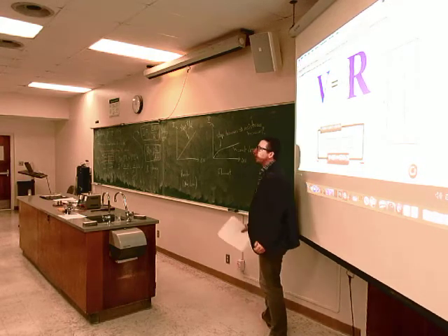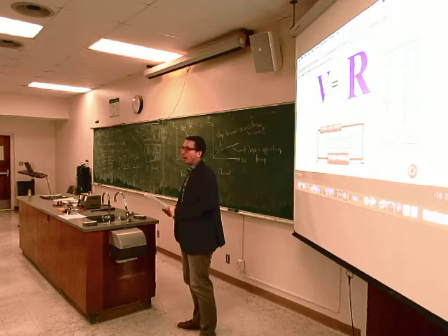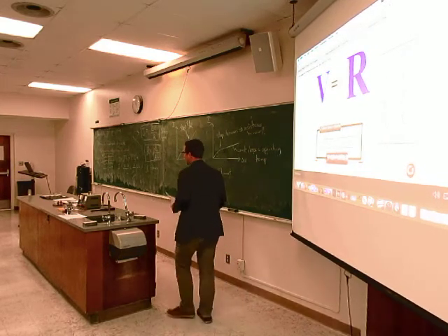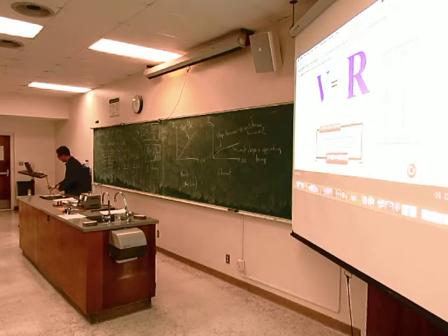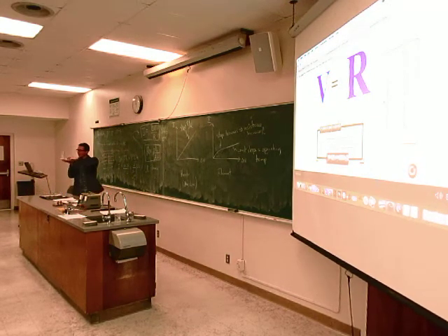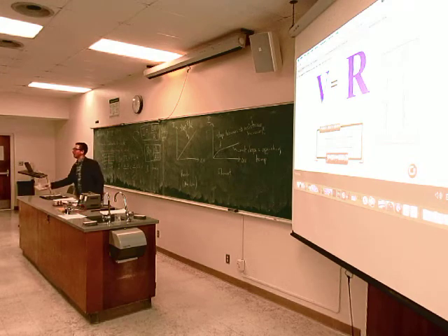The operating temperature for a filament would have to be several thousand Kelvin, right? Which is why you would put a filament inside an evacuated or high vacuum bulb, so that the hot material doesn't burn up or become oxidized. They're very hot. You don't want the filament to catch fire and then break apart from the electrodes, right?